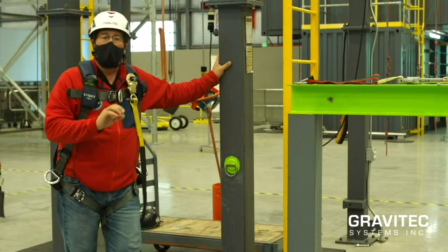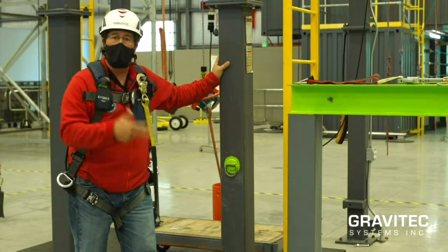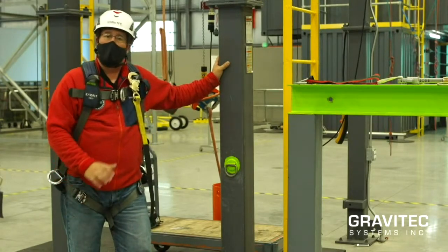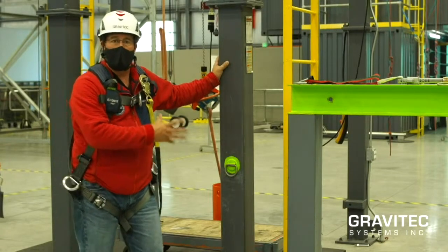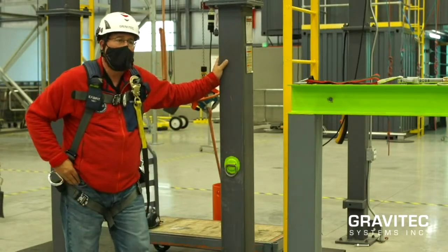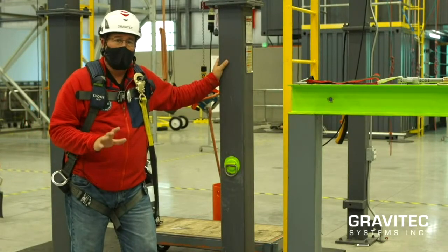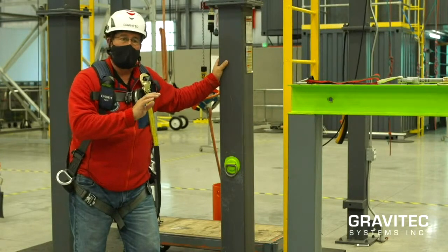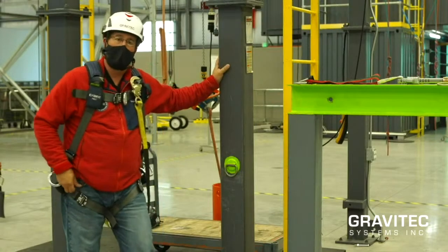So the anchorage goes by several different names: anchor system, anchor subsystem, tie-off, safety anchorage, anchorage point. People use all kinds of different terms to describe this element, if you will. So I'm going to try to boil it down into its most basic format. First of all, anytime you're using an active system, whether it's restraint or arrest, there has to be an anchorage. There has to be something to connect to, okay?